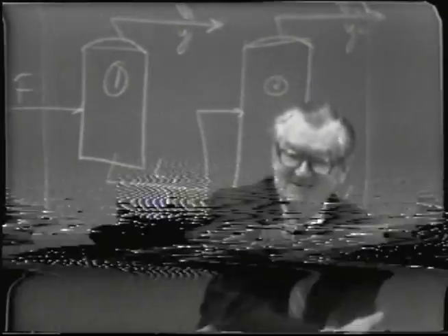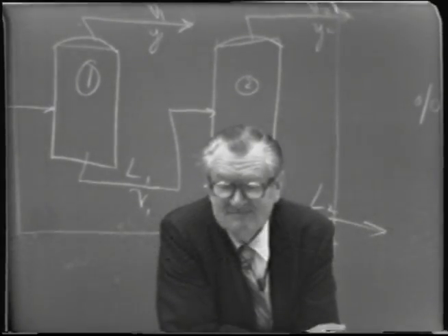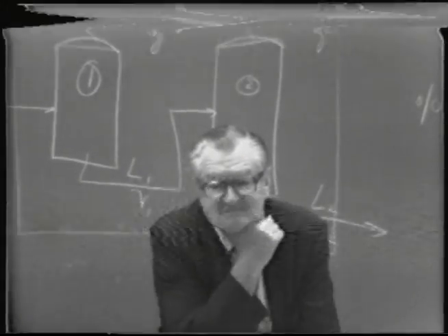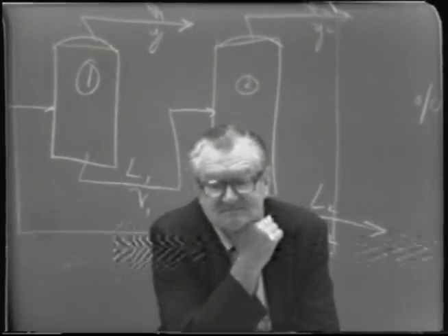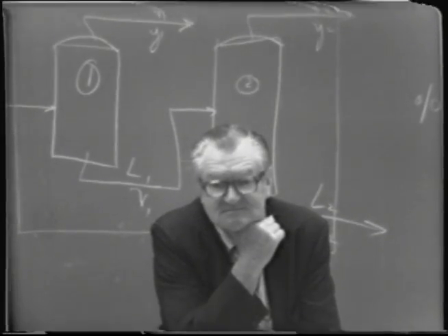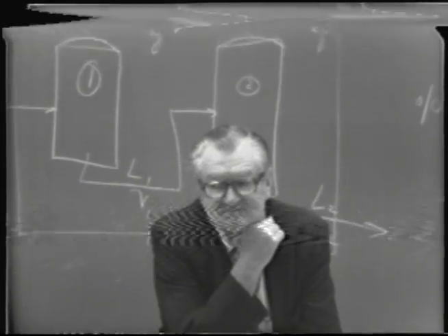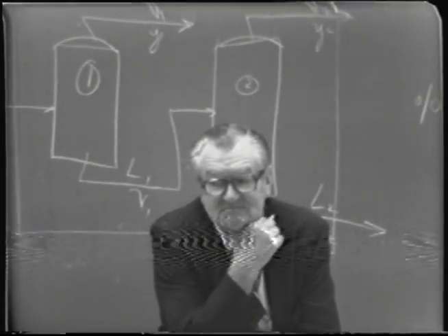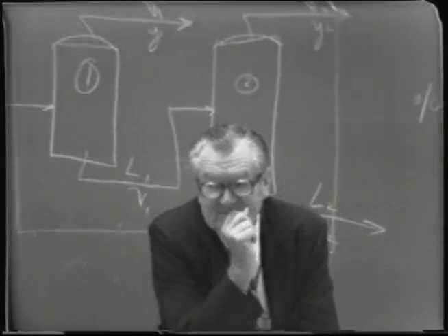No. What did you read? I read it as the percentage of the volatile component in the vapor stream, the combined vapor streams. So I calculated the amount of volatile component in the two vapor streams over the total amount of vapor stream as a percentage. You got 24% in the first one and about 6% in the second one. And then you work out the amount that comes out and put them in proportion to get the average concentration.